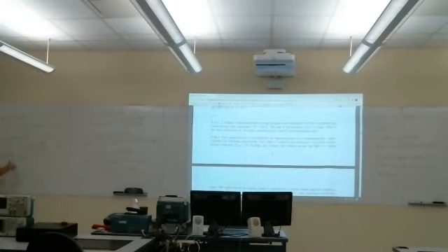And that would be true at this distance plus a distance lambda over 2 longer. So at 2 lambda, at 2.5 lambda, at 3 lambda, 3.5 lambda, we would see this input impedance. But at other distances, you can see something completely different, because this tangent goes anywhere from 0 to plus or minus infinity. So we get various combinations of the load and characteristic impedance.